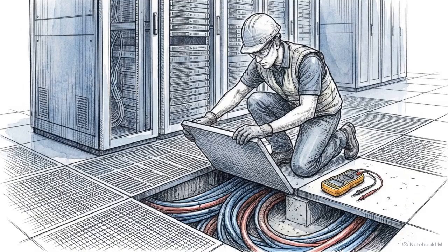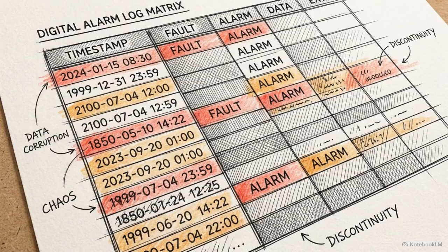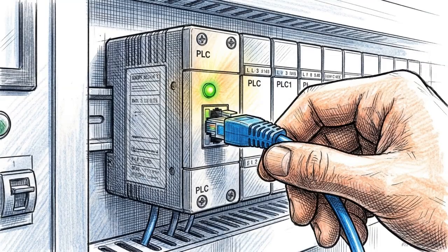The fault remains until the operator traces the symptom backward, physically investigates the source, and corrects the hardware alarm in the field. Because accuracy is critical, network settings and time synchronization protocols in the setup menu must never be altered without formal authorization. Discrepancies in the local panel time destroy the chronological alignment of alarm records during a post-incident investigation. Tracing digital symptoms backward through the physical architecture ensures that localized mechanical trips are not misdiagnosed as a total loss of the monitoring system.